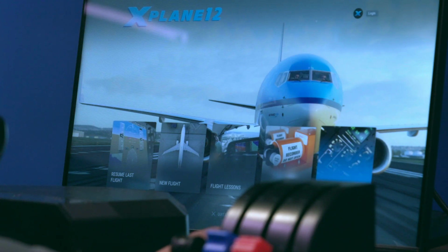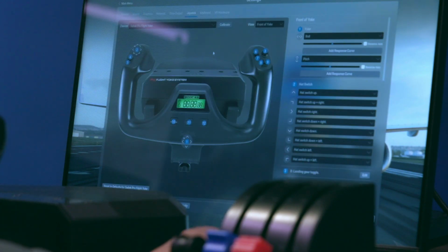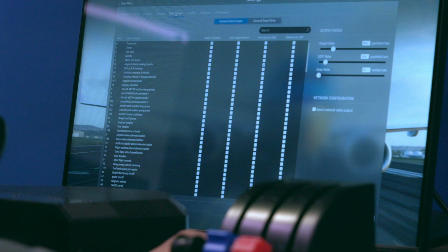Next step would be to, I guess, go back to settings and check the data outputs. We can output a lot of data here. What we are interested in is the lift specifically. You can just search for lift. This should already be selected. As you can see, we are recording the lift over drag coefficient, which is lift over drag, which is what we need, and also lift and drag themselves.